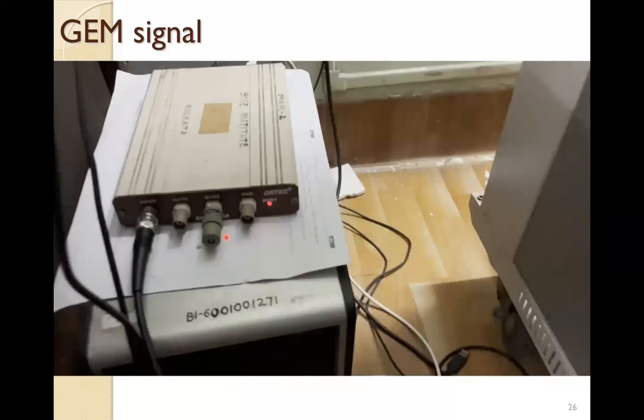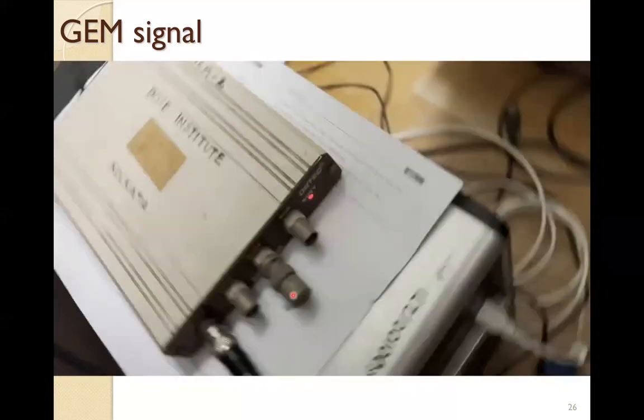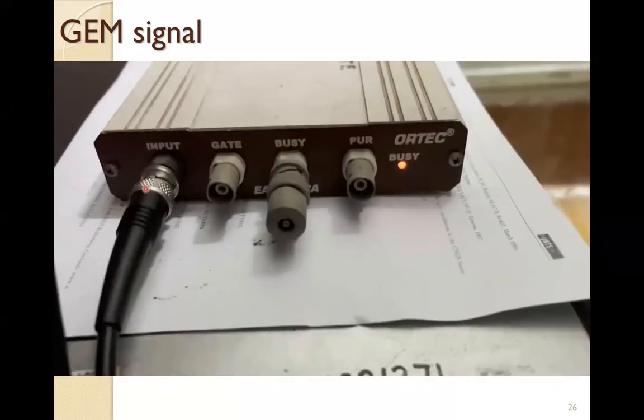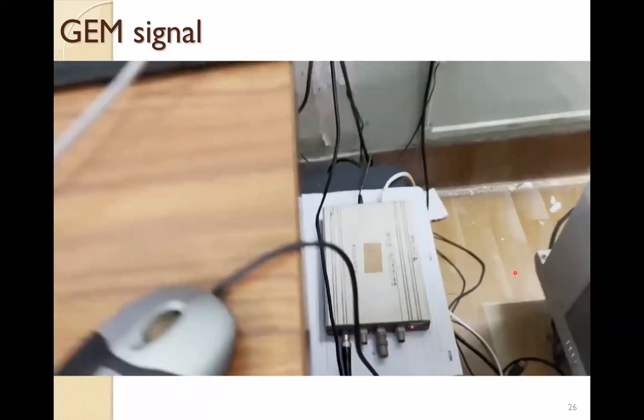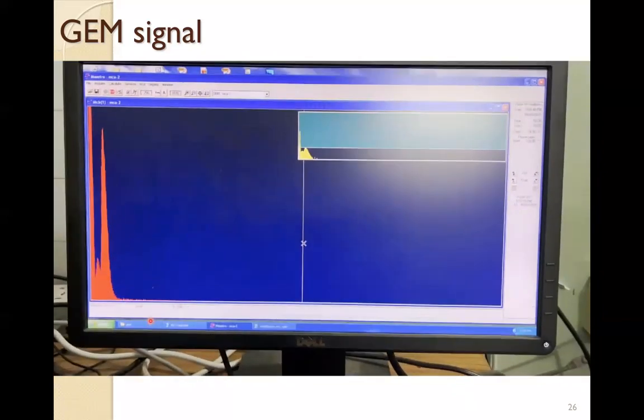So you see what I have shown. This is the main peak. It is accumulating the data, and this is the escape peak. So the resolution is not very good because these 2 peaks are not separated nicely. So this is the MCA. The signal from this FIFO to this MCA is fed using this cable, and this MCA also needs a power supply, which we put from the backside of this MCA.